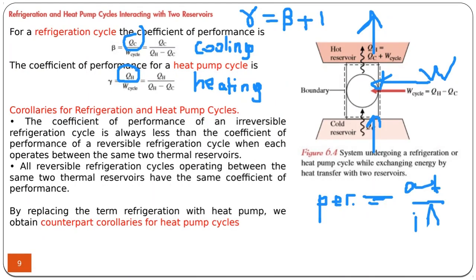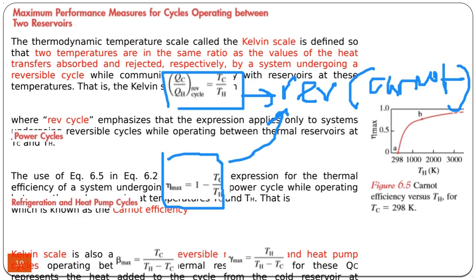And similarly, this is for heating, and this one is for cooling. If it's a Carnot refrigerator used as a heater, then the performance of the system is calculated from the use of temperatures instead of heats added in the low temperature reservoir and removed from the high temperature reservoir.